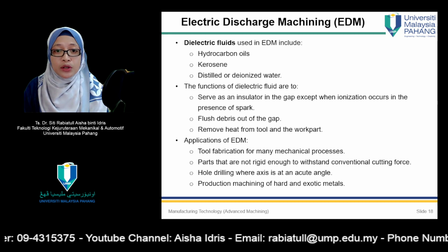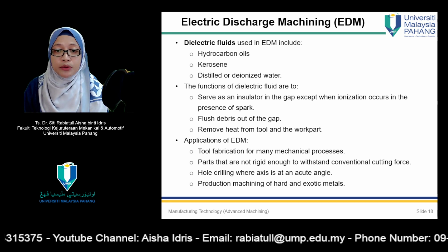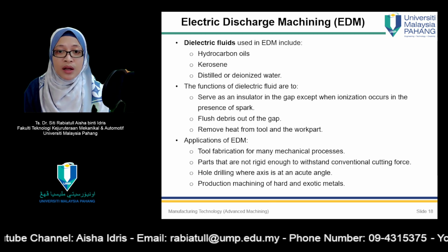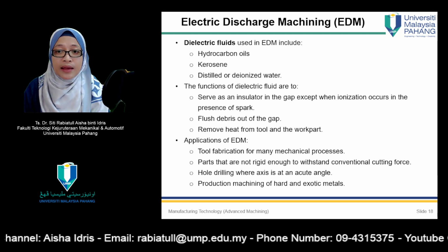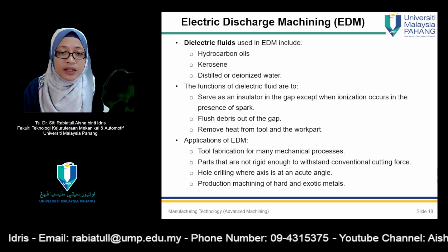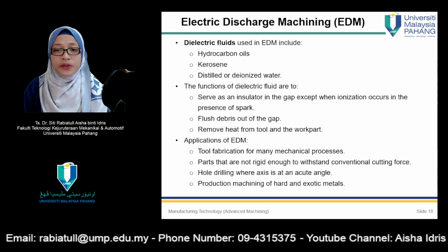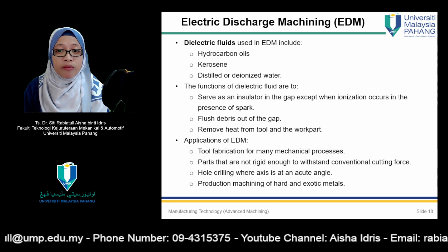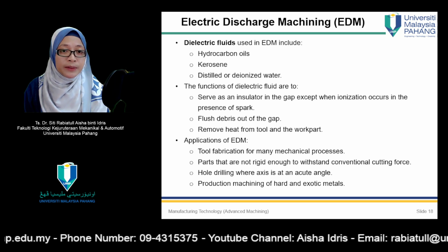Dielectric fluids used in EDM include hydrocarbon oils, kerosene, or distilled or deionized water. The dielectric fluid serves as an insulator in the gap except when ionization occurs in the presence of a spark. Its other functions are to flush debris out of the gap and remove heat from tool and work part.